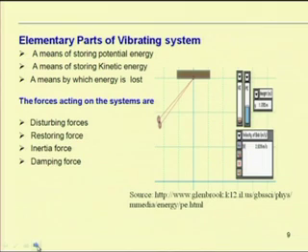So, one has to apply a disturbing force and then it will come to a position where all the energy is converted to potential energy. Here it is subjected to a restoring force, and when it is coming to this equilibrium position, the velocity becomes 0, but due to inertia the system is subjected to a force and it comes back in this direction.